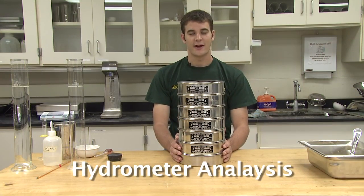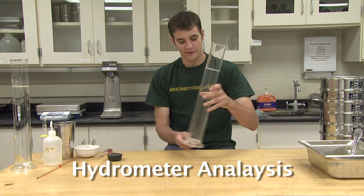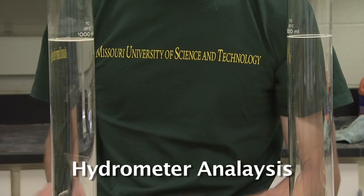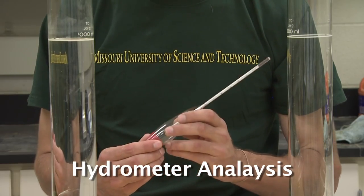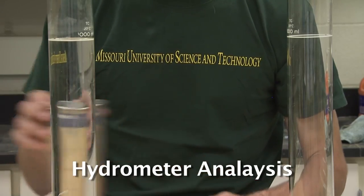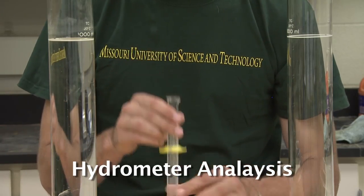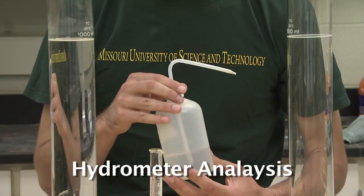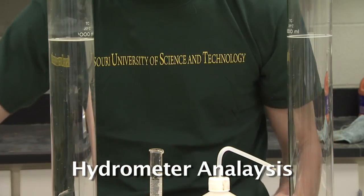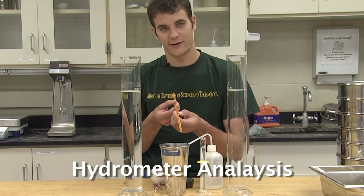In order to conduct a hydrometer analysis, the following devices will be required: a 1,000 milliliter sedimentation jar, a 1,000 milliliter control jar, an ASTM 152H hydrometer, a soil dispersion device, in this case a shake mixer, a soil dispersion agent, in this case sodium hexametaphosphate, a squirt bottle filled with water, an evaporation dish, a rubber stopper, and a thermometer measuring in Celsius.